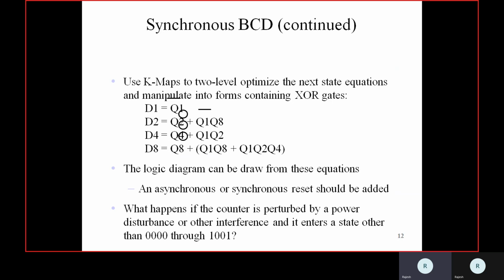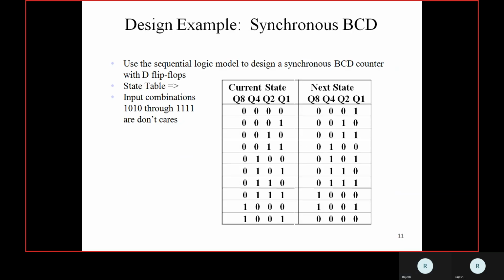Okay. So like that, it will count from all zeros to all ones. It is a 4-bit counter. It is a mod 16 counter, 0 to 15 it will count. If you make it a mod 10 counter, it will count from 0 to 9.